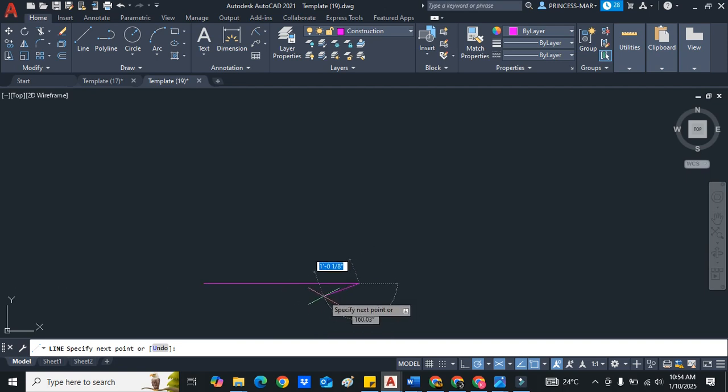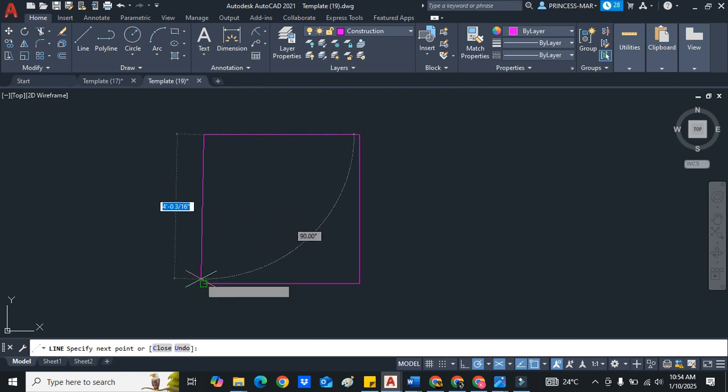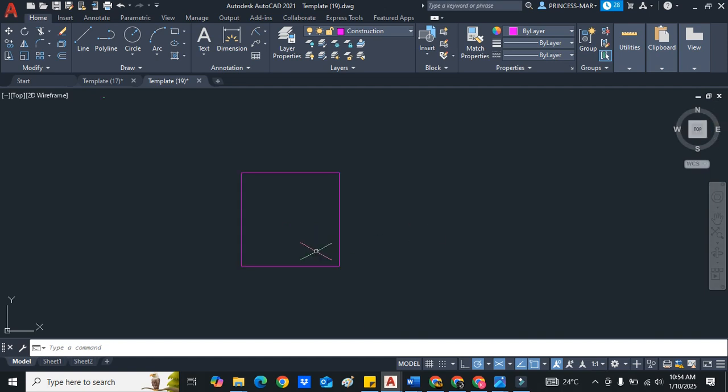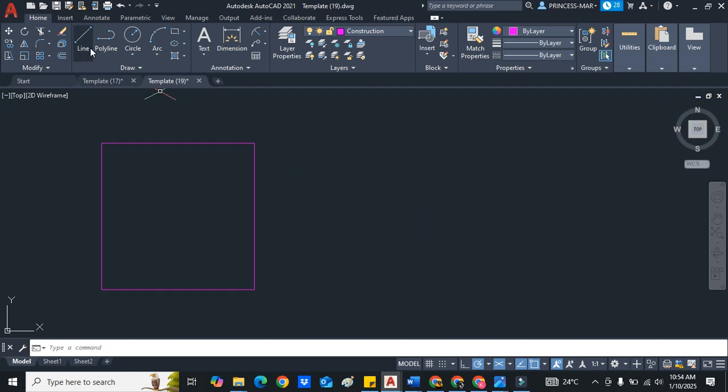So this line that is drawn is at 50. I angle the mouse up. I do not click anything on the mouse. I'm just moving it to an angle. Straight up, 50 on the keyboard, press enter, angle the mouse to the left, 50 on the keyboard, and I press enter, and then I bring the line going down here, and I left click to end it. To turn off the tool, I click escape. So if I wanted to zoom in or zoom out, I would use the mouse wheel to zoom in or zoom out.